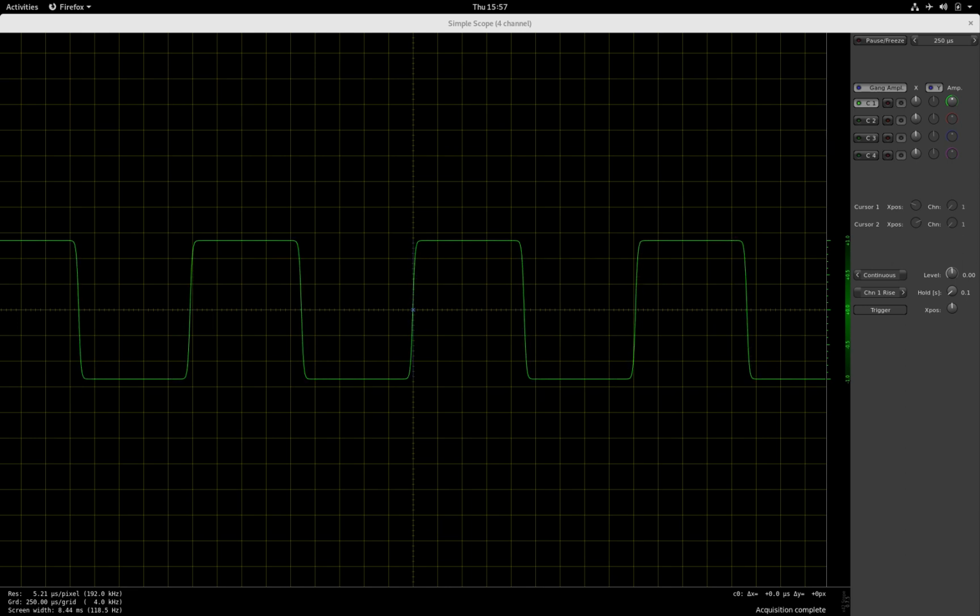Now we have the gain up again at 30 decibels, and now we will decrease the drive value instead. And this is what happens to the signal. You will notice the signal will no longer clip that hard against the supply voltage. The clipping will get softer, but the slope through the origin will remain pretty high.